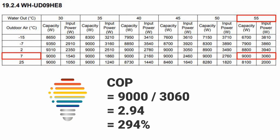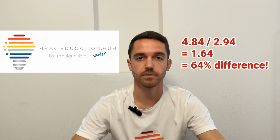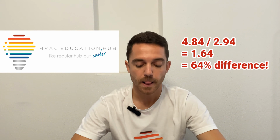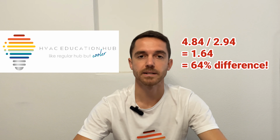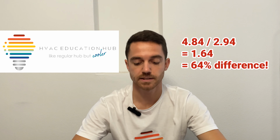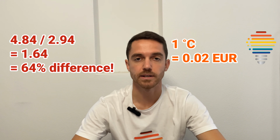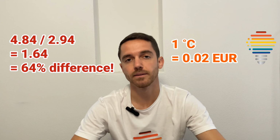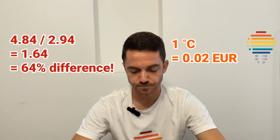It means 294% efficiency. If we compare 35 degrees flow and 55, the difference in COP is 64%, which is a very high difference. It means that for each 1 degree of increase in flow temperature, we spend 2 or 3% more electricity, or more running cost.